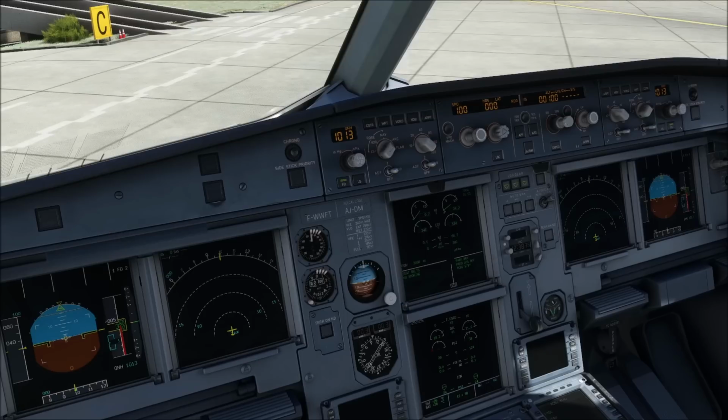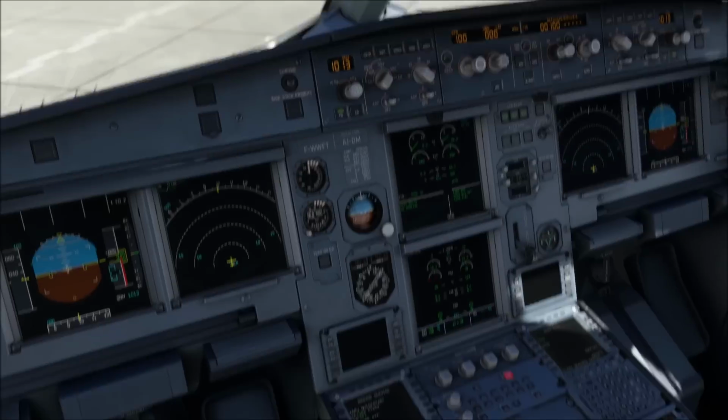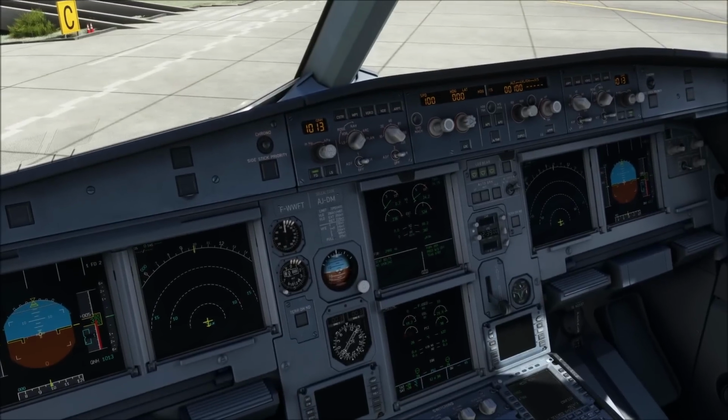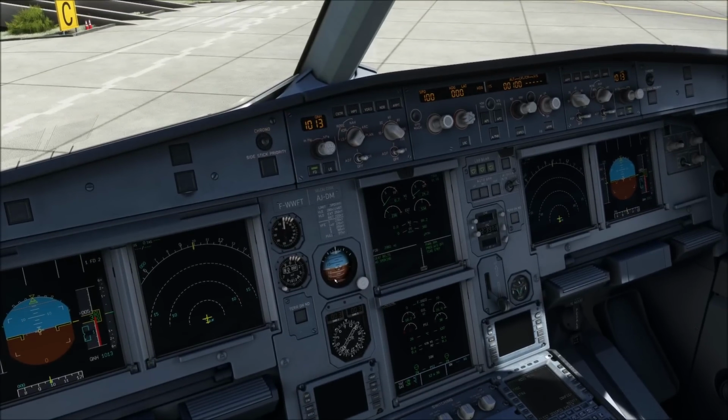Caution: do not perform the cross-bleed engine start procedure during a pushback. Simultaneous use of engine bleed supply and external pneumatic power is prohibited. So, especially when you came previously from the engine start with an air start unit procedure, you want to be sure that the ground power and the ground air are disconnected. Okay, one engine must be running in order to supply air for the other engine start.